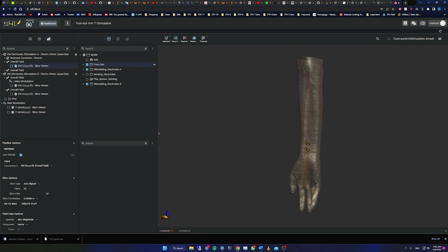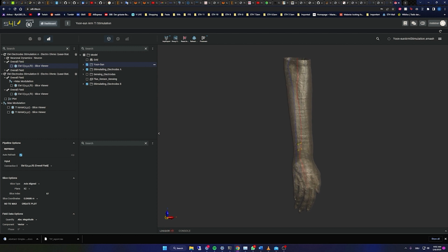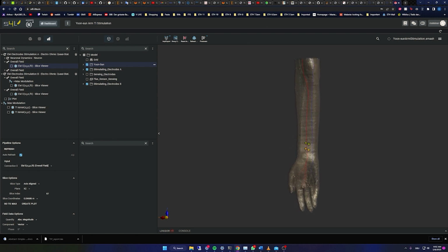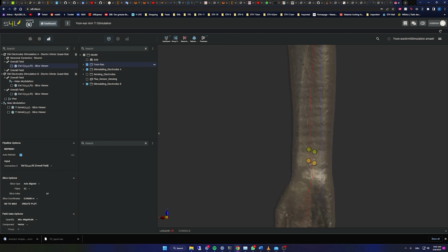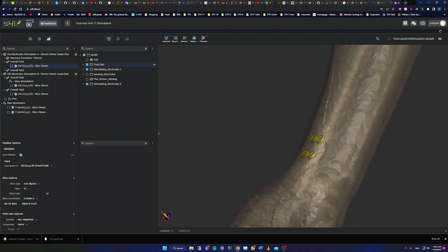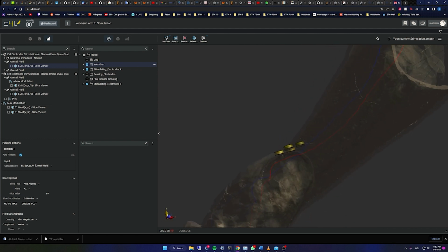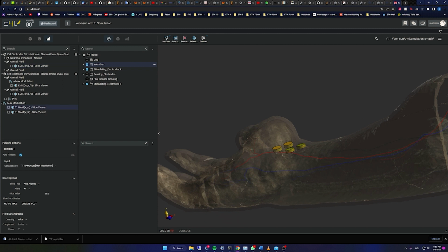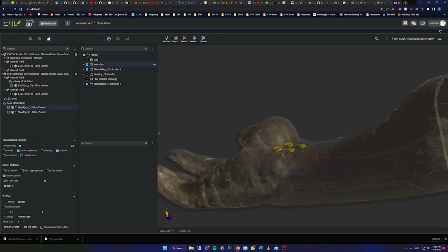Temporal interference stimulation uses two intersecting currents at frequencies that on their own are too high to elicit a neural response. However, because they have a slight frequency difference, a low-frequency beating effect ensues, which affects neuron activity. Here I want to see if it is possible to use TI stimulation to non-invasively and selectively stimulate the median nerve in my forearm, without causing pain, sensation, or muscle twitching near the electrodes. Various strategies are possible. I could place the electrodes in series, in parallel, interleaved, or in a nested arrangement.